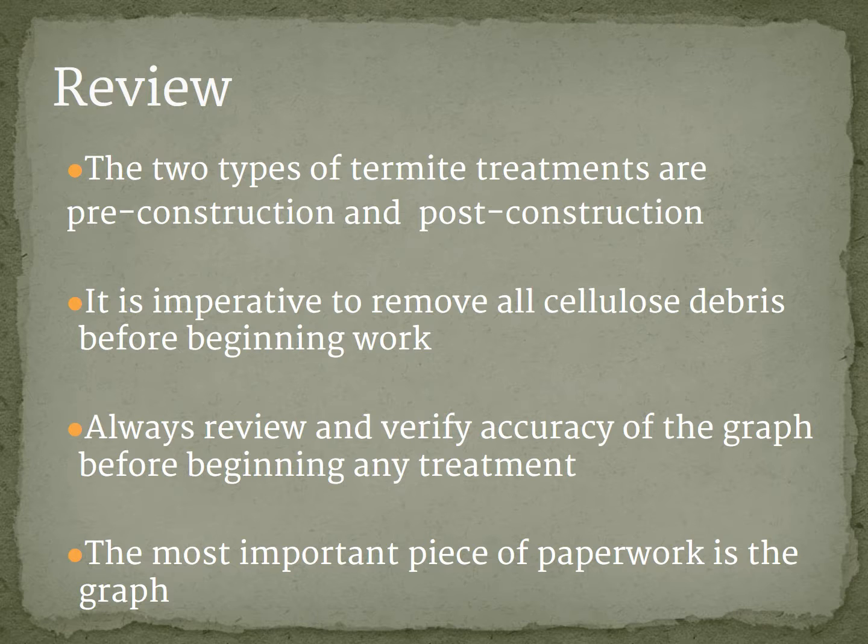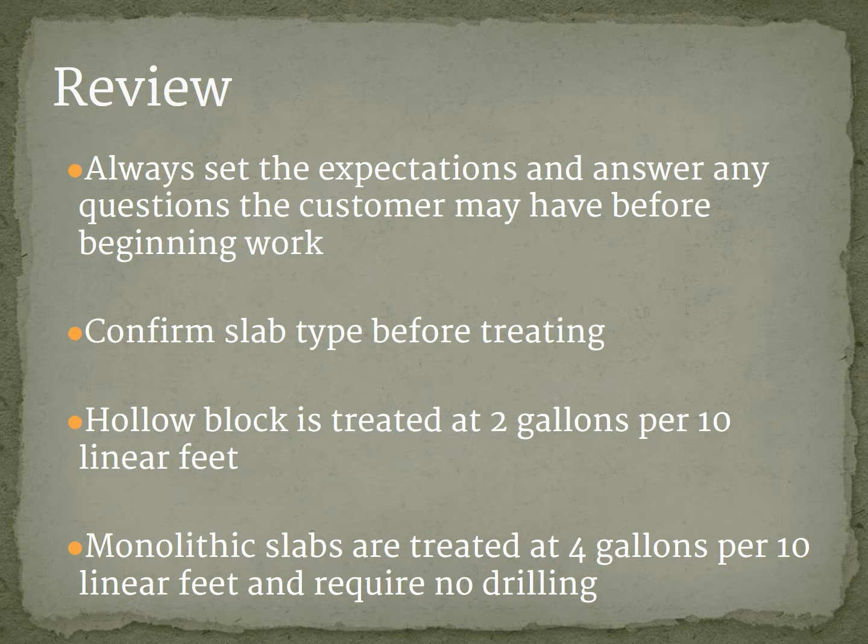Let's review what we've just learned. There are 2 types of termite treatments: pre-construction and post-construction treatments. It is imperative to remove all cellulose debris before beginning any treatment. Always review and verify the accuracy of the graph before beginning any treatment. The most important piece of paperwork on any treatment is going to be your graph.